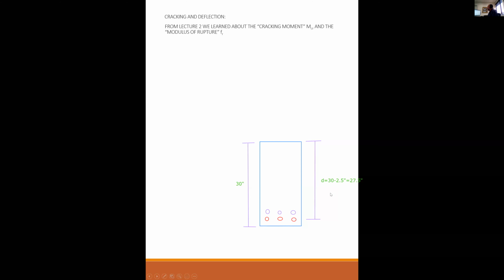But you didn't recalculate D from your chosen 30. So when you went to 2 rows, either 30 gets deeper or you have to recalculate D, which is now equal to 30 minus 3.5 inches. So D is only 26.5 if you keep the 30. That's what the point was about. Okay. So it's either I shorten the D or make the H longer? Yes, that is correct.